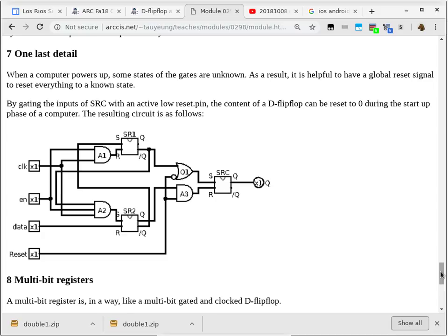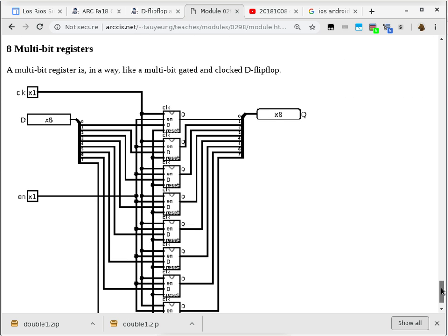So I'm just telling you all these things because it's sort of related to the reset line, but they're all inside your processor and also your phones. Your Android phone and your iOS phones have the same kind of mechanism. So sometimes when your phone enters a really bad state, it will reset itself, and that's because of the watchdog mechanism not getting confirmation that everything is still good. So it just instructs the phone to reboot itself.